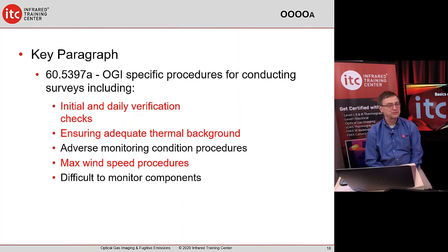And the gas cameras work on the principle that the gas is going to absorb energy from somewhere, and it's not going to make it to the camera. So the background is what you're looking at, and the gas would be between you. You have to make sure that you just have enough sensitivity there. And I've tested these cameras down to ridiculously low levels and have still been able to see very, very, very small gas leaks, but I'm not quite sure, it might be under ideal conditions.